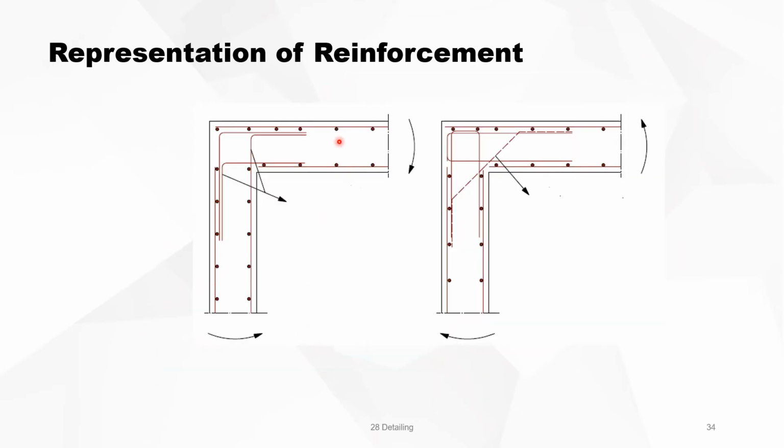This is a closing corner. This is a typical reinforcement of closing corner, taking care of the bending moment on the outside. And this is a typical reinforcement of an open corner. When a corner is opening, then you see that this is a stirrup doing that, and this is a stirrup doing that. And this is the best way of reinforcing a corner, because it's a mechanical interlocking. This bar is needed when the forces are relatively high. So for high constructions and things like that, this bar is needed because you have tension here on this side.